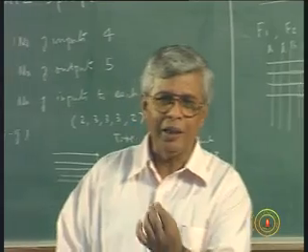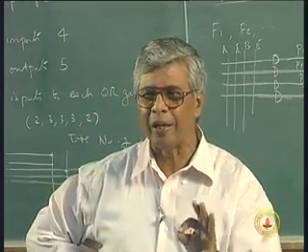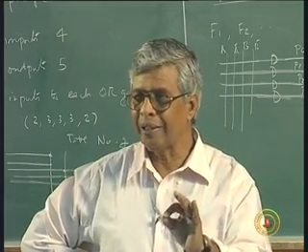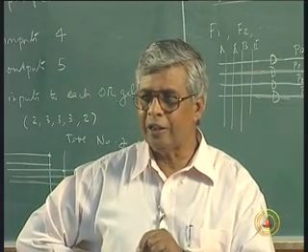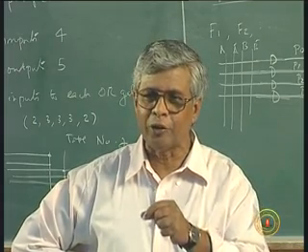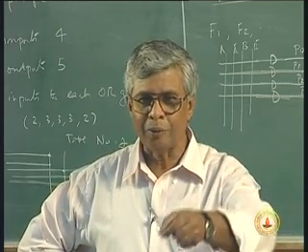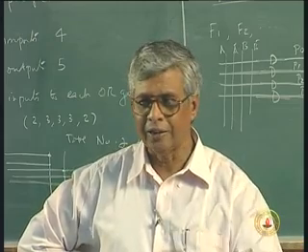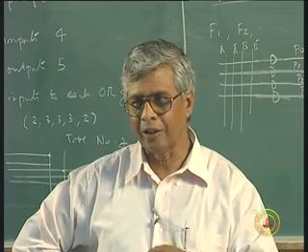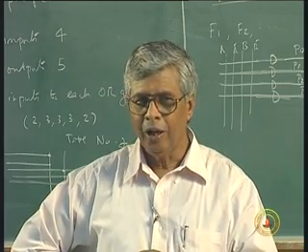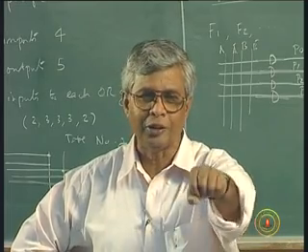I may put a million gates in a small IC, small area, because we are talking of dimensions of nanometers today, microns and submicrons. But inside you can do anything, etching and all that, electron beam lithography, so that you can make a line as thin as the size of an electron or molecule, molecular epitaxy, electron beam epitaxy, laser epitaxy and all that, laser etching and things like that. But then I put 1 million gate functions, and then I want to seal it and give it to you as a customer.